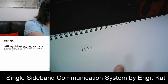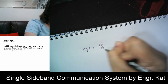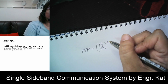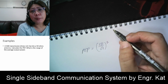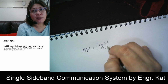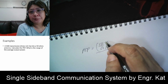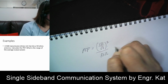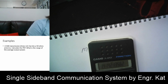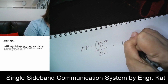So what is the RMS value if we are given the peak value? That is just equivalent to 121 divided by square root of 2, squared. From peak, we just convert that to RMS. If what is given in the problem is already in RMS form, we don't need to convert anymore. But we are given the peak value instead. Divided by R, our resistance is 50 ohms. So this is 121 divided by square root of 2, squared, divided by 50. That will give us 146.41 watts.